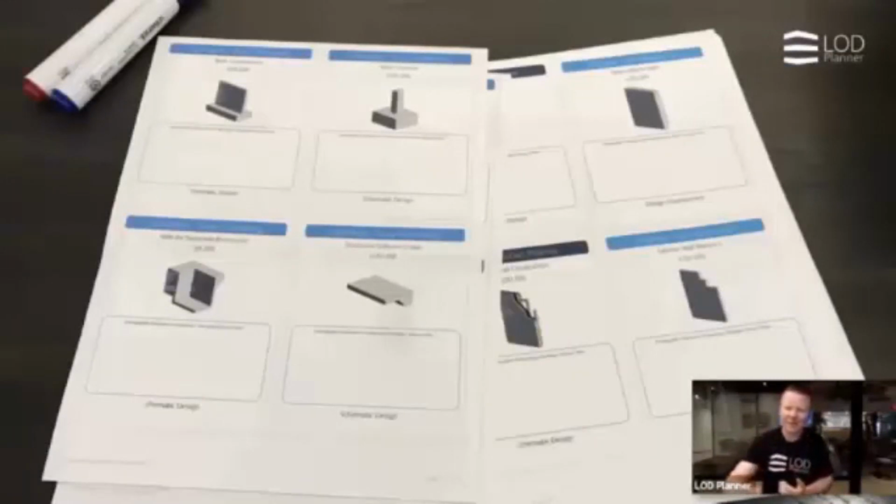But then, as I mentioned, to achieve this avoidance process, the clash avoidance process, it's all about sequencing those elements. So the best way to have feedback is when you're in person. We have video, which is great, but when you have somebody right next to you and you can have a conversation and you can achieve an understanding of, I need to put my ceiling in before you fix your light fixture at that elevation. Otherwise, if I put my ceiling in afterwards, you'll have to move your light fixture. So therefore, the sequence of those events is incredibly important.